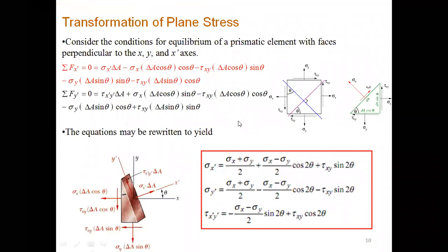The stress element is in equilibrium, because the stress element represents the stress values at a point, the point which represents the particle inside the material. When the material is loaded, those particles are not rotating. They are in equilibrium, they are static. So we can apply the condition of equilibrium and statics on the particle, on this point Q, on this stress element. So the stress element must be in equilibrium.